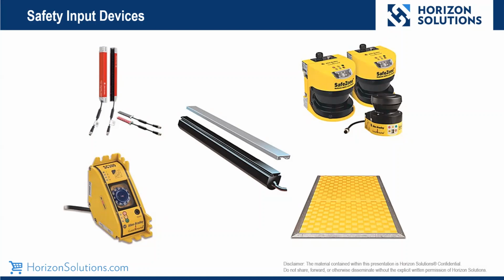This is one of the biggest determining factors in using an optical sensing device. So here in the top left-hand corner, we have a set of 450L light curtain sticks. These are set up for what's called finger detection, which is a 14 millimeter resolution. This means that an object with a diameter of 14 millimeters or greater is guaranteed to be detected.